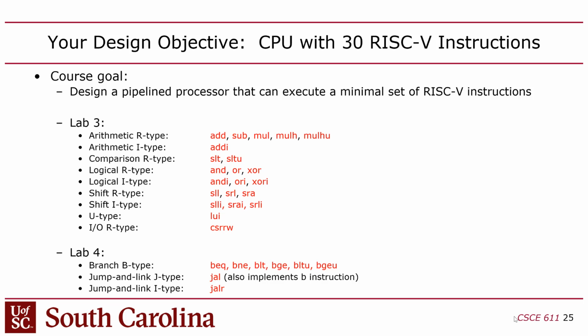So the final project in this class, because we've added a lot more, we've scaled back the projects a little bit, but right now the final project is to design your CPU and then write a short assembly code program that will make this board behave like a calculator, where you can select an input value using these switches, and then the processor and your program together, the hardware and the software, will calculate the square root of the value that you put in, and it will display that on the hex displays, on the little 7-segment displays. So the value you put in will be an integer, but when you calculate the square root, it's going to be a fractional number more than likely, right? And so the hex displays will display the fractional number where the first 3 digits are whole numbers, and the other 5 digits are fractional digits in base 10.